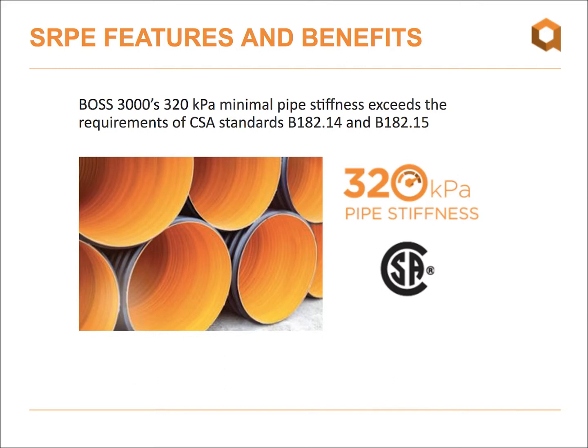So it means that if in the past you've been using flexible pipe 900 millimeter and smaller and have enjoyed great success doing this, you don't need to worry as you migrate to a larger diameter pipe, because this larger diameter pipe offers you less stiffness. It used to be the case in the past, but now our pipe offers you the same stiffness. So the installation methods that you were using will translate and will be replicable in the larger pipe sizes.